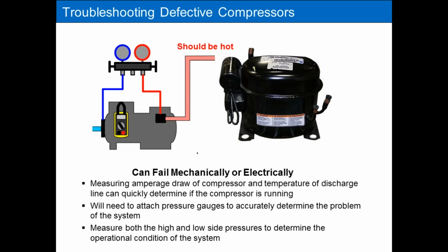All right, let's talk about defective compressors. That's pretty common. You're going to come across these units that have a compressor that is giving you grief, and that's causing the case temperature to be hot. Compressors can fail either mechanically or electrically, and we're going to talk about how to determine which is which. Here's a quick way of starting the process of knowing that your compressor is part of the problem. What I normally do is take my ammeter and put it on the common lead, one of the electrical connections leading up to my compressor, and I want to measure an amperage.